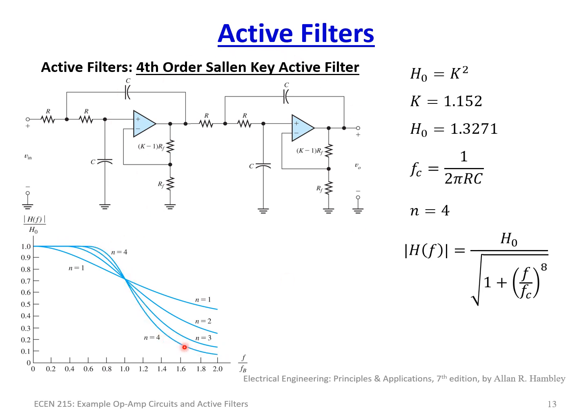There's a very sharp cutoff, so this is very effective as an active filter, as a high pass or a low pass filter, or you're thereby creating a band pass or a band reject filter. You can use these in that configuration by just changing where your cut on and cut off frequencies are located. Now, the interesting thing here, where N is equal to 4, is this flat band.